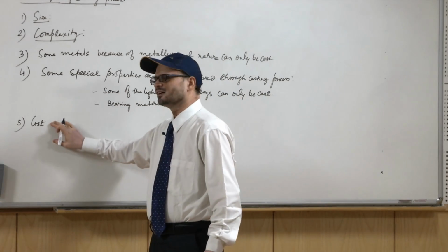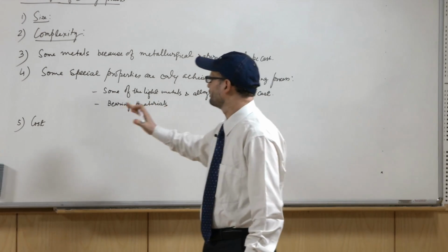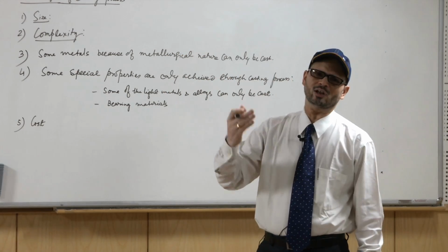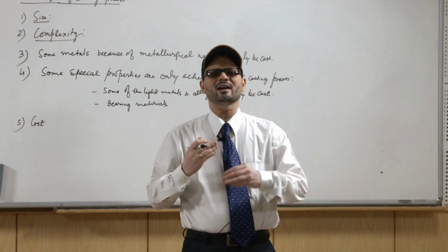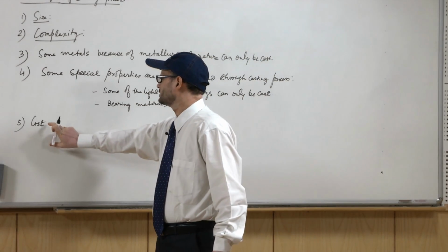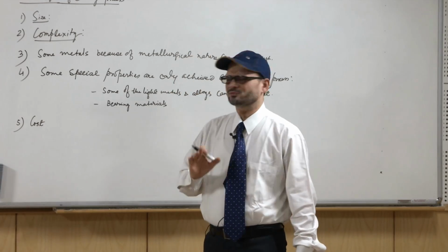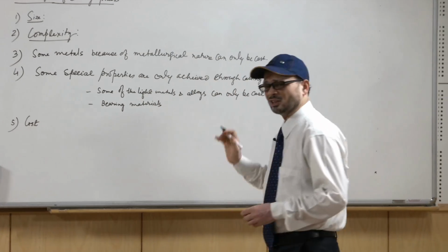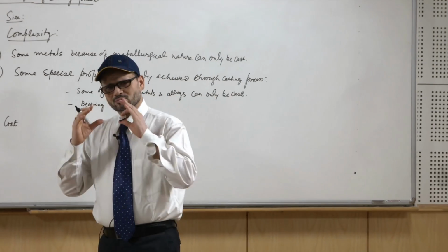In that case, the cost of the component through this route is minimum. So, when we talk about mass production, casting is the only way to go. If we are getting specialized properties, then only we have to think about it, and at that time this factor becomes very important, and that way casting is a preferred process by which we get the material in the desired shape.